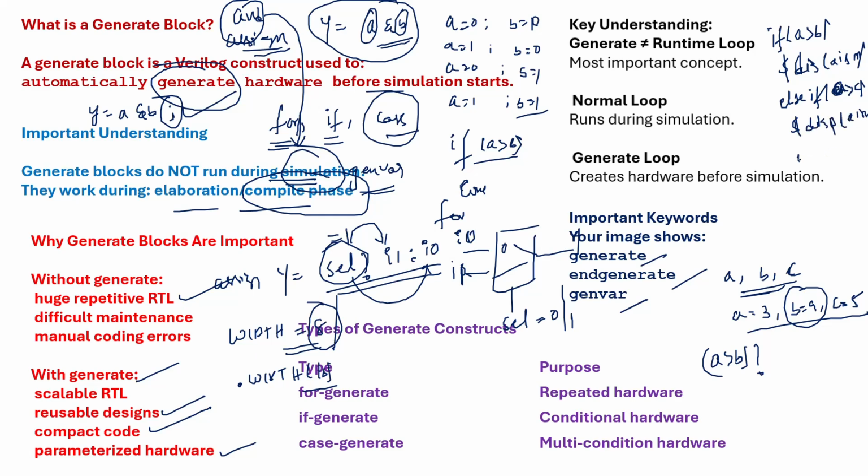And false means else if condition we will write. What is the condition we can write? Else if B greater than C. B greater than C means what is the value? B is 9 and C is 5. The condition is true, then you will get the B value, right? $display B value we will get, and else condition $display we will get C value. Then I know which one is the highest value.